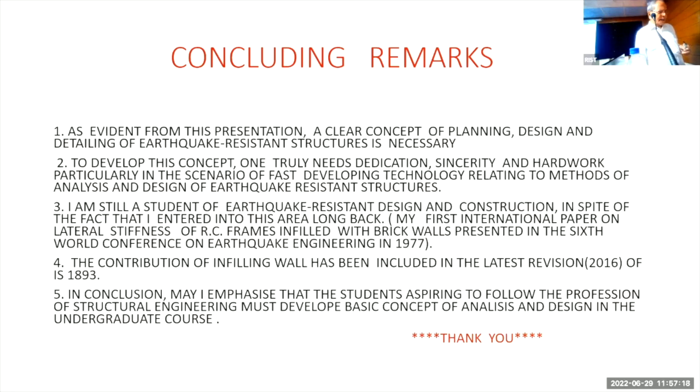Then fourth one, the contribution of the infill wall. In the recent revision of the code, the research on this topic was started long back. I remember papers of the 1960s. So in this same structure, I have this wall, these two columns and beam. When an earthquake comes, lateral forces act on the building, and this wall contributes a lot in the resistance of the lateral force. But in our design methodologies, the contribution of that wall was not used. And it is only recently, in the revised earthquake code, that the contribution of this infill wall has been taken into account.